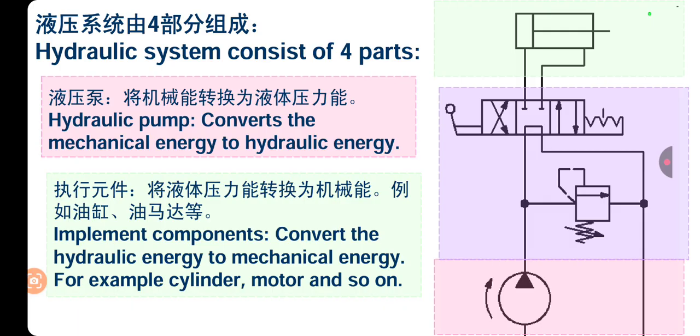The next thing is actuator. What is actuator? Actuator is a device which converts hydraulic energy into mechanical energy, because the pump gives us the hydraulic energy, and that hydraulic energy needs to be converted into the mechanical energy, because we want to take some output from the actuator. For example, bucket, boom, arm, and even travel motors. There are two types of actuators: rotary actuators and linear actuators. Cylinder is a type of linear actuator. All right. So this is all about the basic hydraulic system.